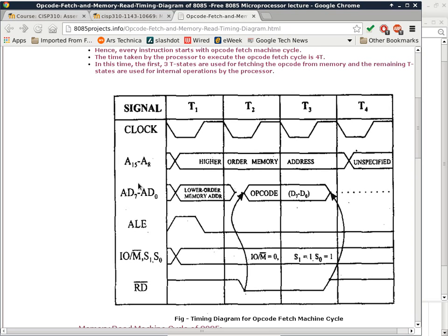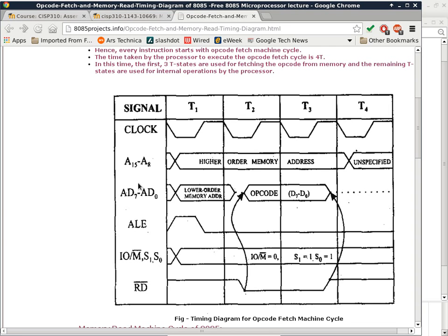So what do you do? Well, if your resources are limited and you only have a few traces that you have to cross over, what people do is they solder wires on one side of the board, and then they solder the other end of the wire onto the other part of the board. But that's very labor intensive because you're talking about soldering all these little wires by hand on the circuit board. That's why they move on to more layers so that they have more routing resources. Routing resources refers to the ability to make a lot of connections crisscrossing in all directions and be able to finish the routing using automated tools.